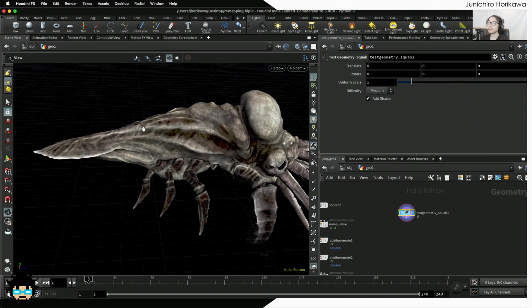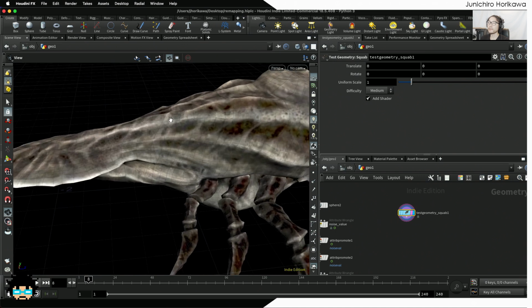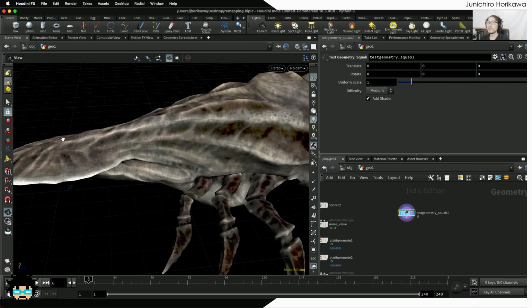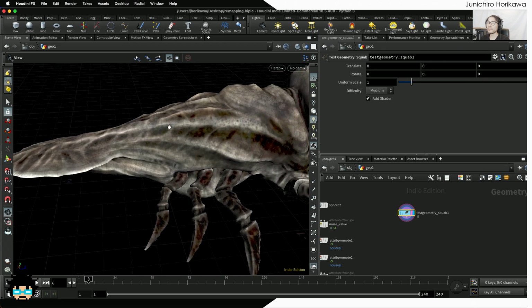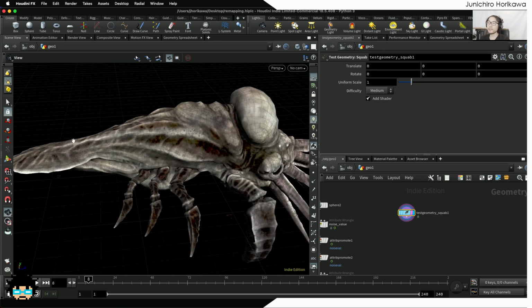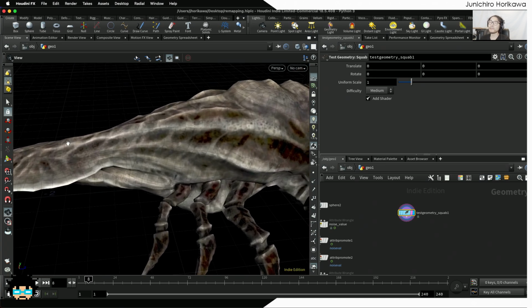for this surface. So what I'm going to do is to change or remap the distance, which is on the surface, to an angle for the trigonometry function like the cosine or sine function, and use that cosine or sine function value to change the height of the surface. So in the result, you should be able to get a wavy surface using the center point as the center of the wave.